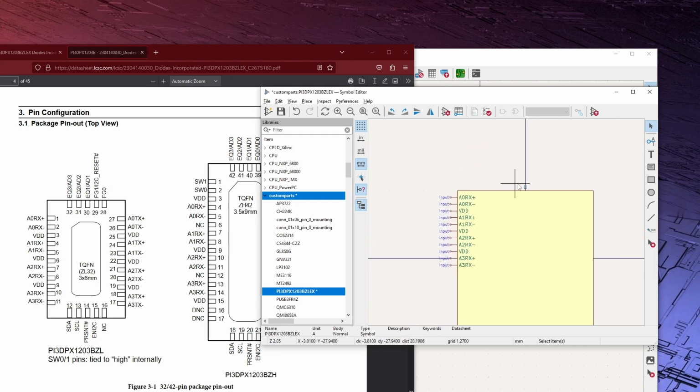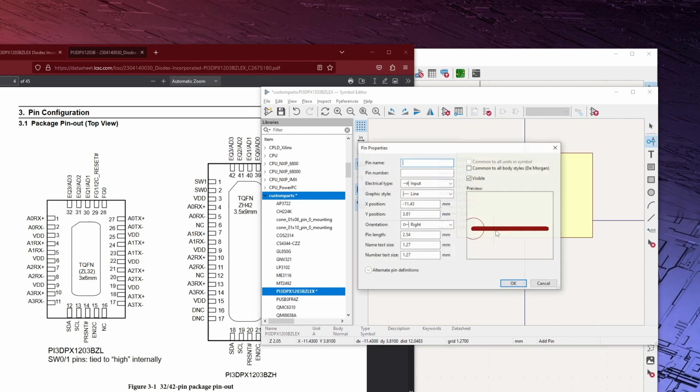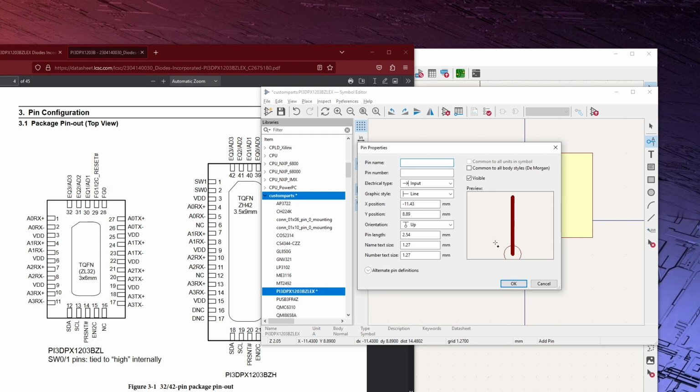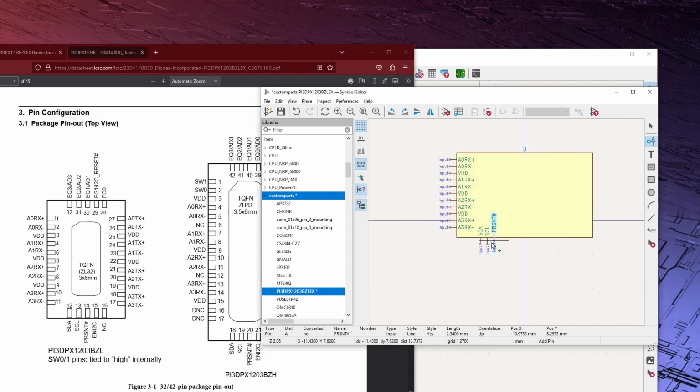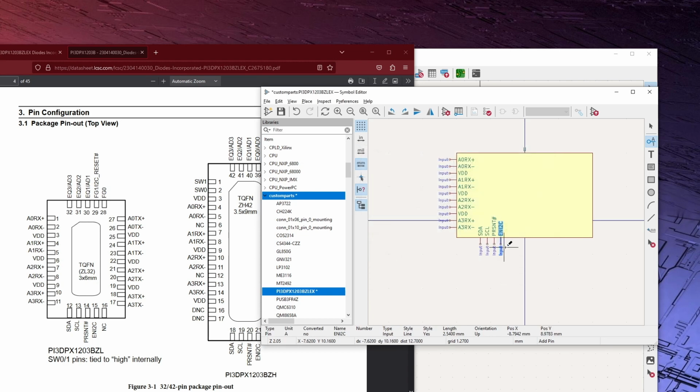Alright, keep going. Now, we can make this a little smaller. This can be a little too big. Right? Now keep adding pins. SDA and SCL are our I2C pins, for configuring the chip, telling it how we want it to operate, that kind of thing. Let's see, PRSNT#. Probably some kind of a present signal, so maybe it would detect if DisplayPort is connected. I'm not exactly sure. I2C, that, I believe, enables I2C.